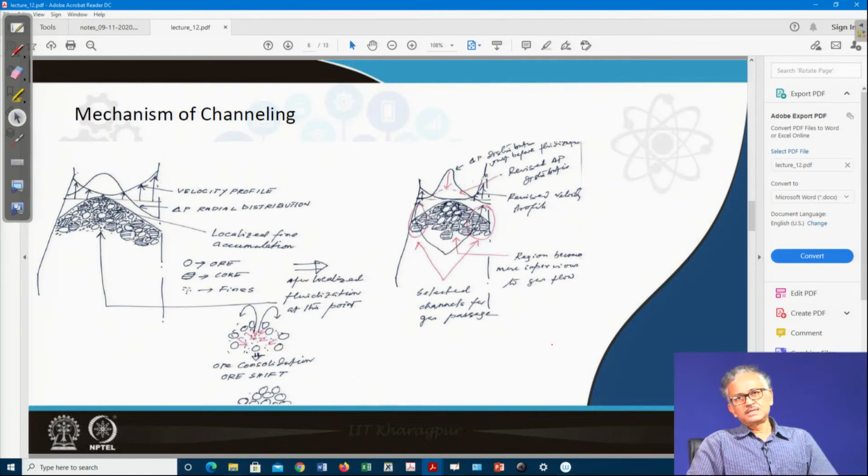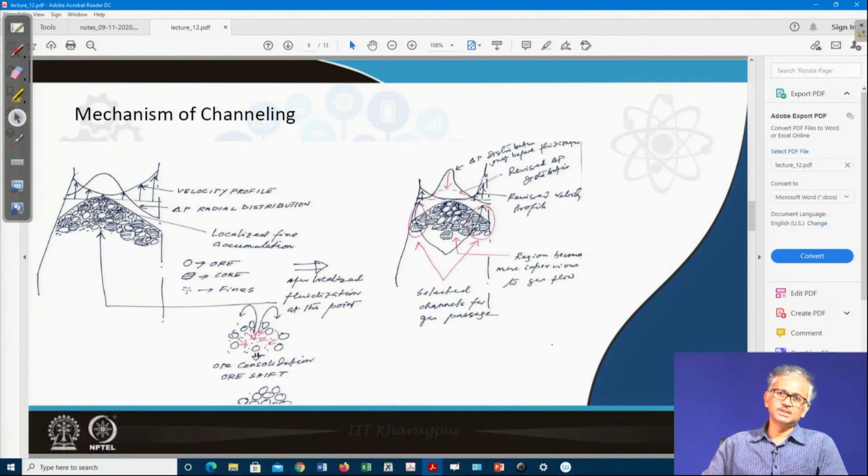So, based on the underburden probes, based on the mapping of the local pressure drop, you can always monitor it. If the pressure drop is increasing someplace, you can make it permeable by charging some coke in that location, and that is the way you can take corrective actions.